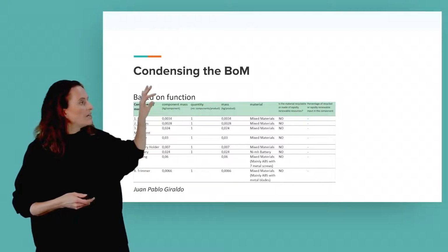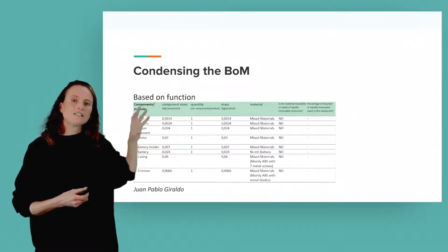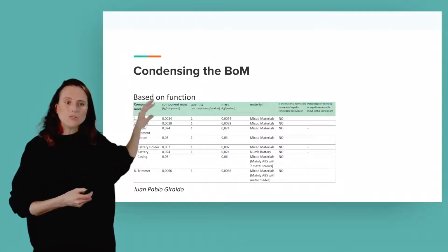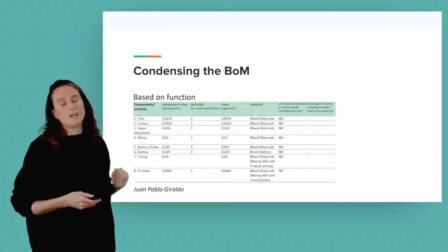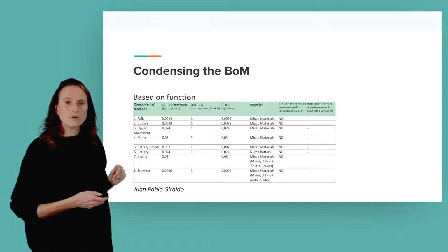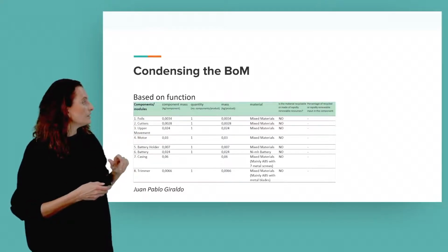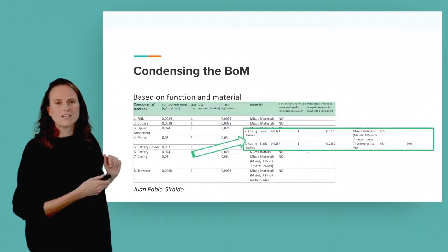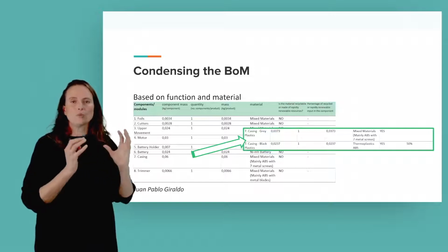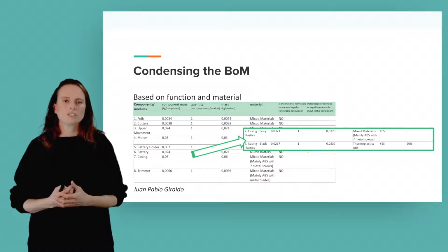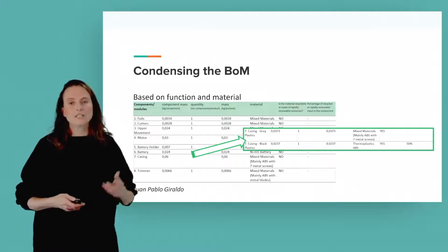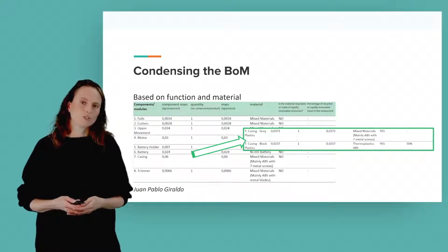What you can see here is that he has many components with mixed materials. What you could do in this case, because it were only 8 components, is to split the heaviest mixed material component, which is the housing here, the casing, in 2, with all the ABS parts in one module and the remainder of the parts in another. So you can easily say which of the 2, or in this case both, are recyclable because you consider them separately.